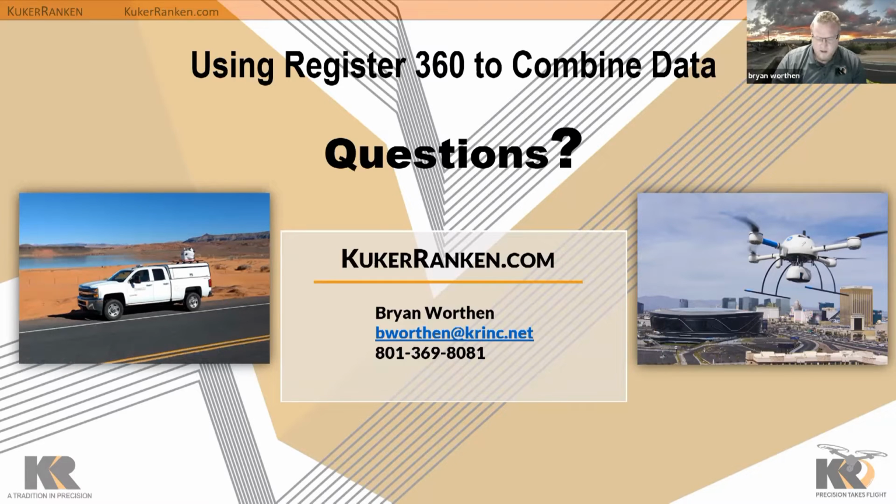That'll help. And even if you have an RTK drone, which I do suggest everyone run an RTK drone, you can create the same kind of results with a non-RTK, but you don't get the efficiency. RTK gives you much more efficiency with not having to add as many targets. You still have to add targets, because you want something to constrain it.